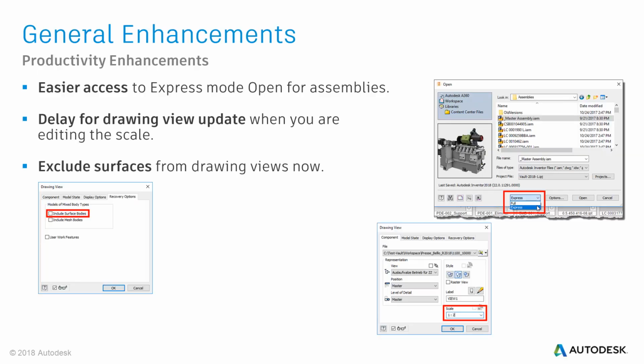Okay, let's get started with the general enhancements in Inventor 2018. Beginning with an easy thing. The Open dialog offers an easier access to the Express mode now. Instead of clicking through the Options button, you directly access the Full or Express mode in the shown drop-down menu.